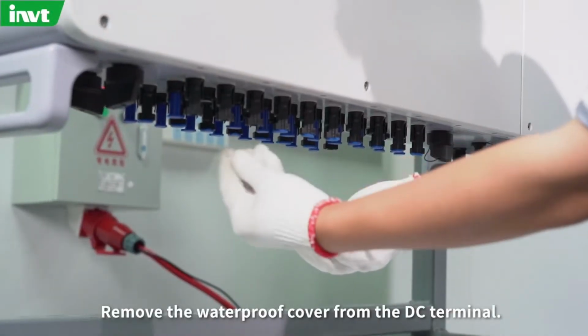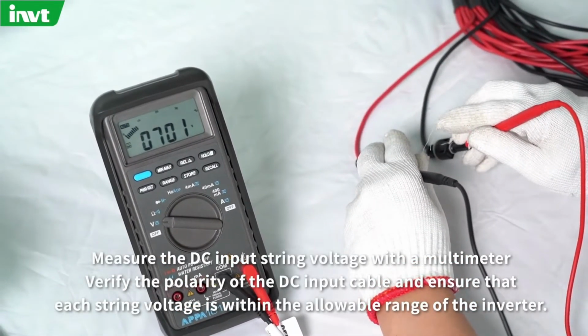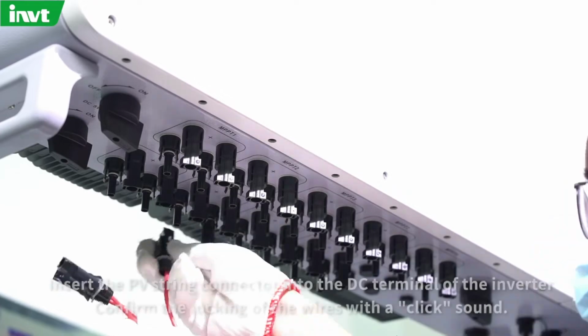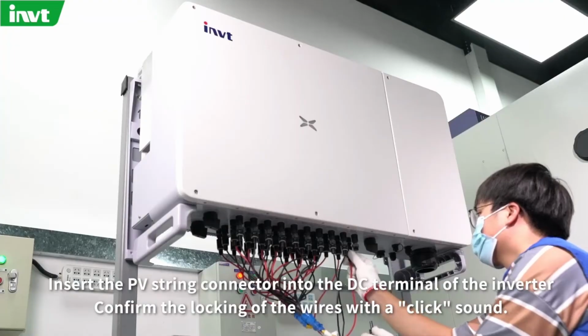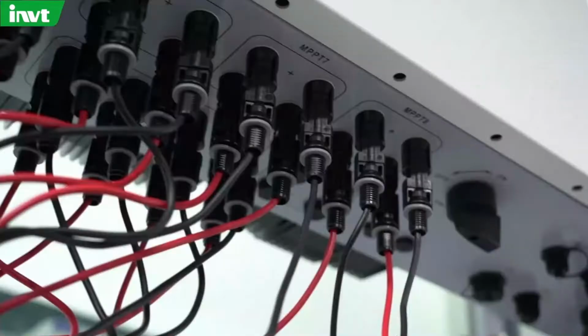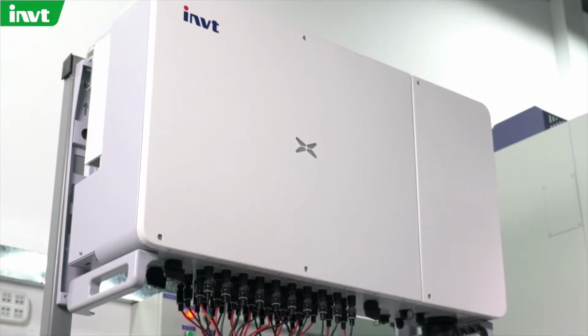For the solar inverter with larger power, each MPP tracker has multiple DC interfaces. The wiring of PV strings should be well marked and properly wired to avoid mixing different numbers of strings on the same MPP tracker, resulting in PV panel mismatch and power loss.